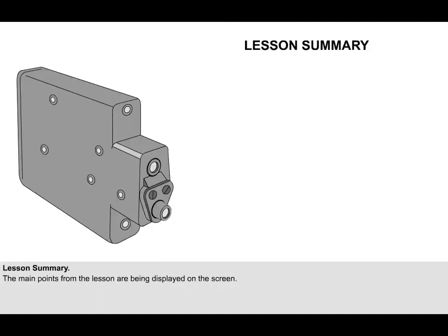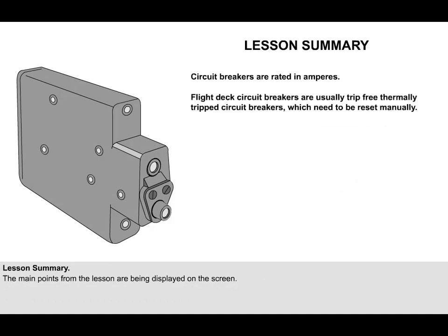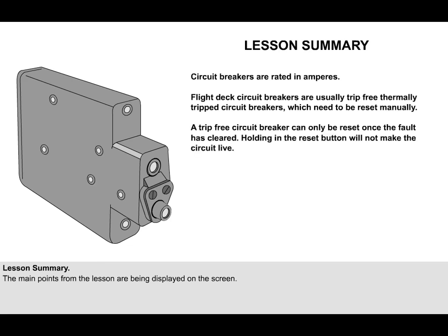That is the end of the lesson. Remember the following key points. Circuit breakers are rated in amperes. Flight deck circuit breakers are usually trip-free thermally tripped circuit breakers, which need to be reset manually. A trip-free circuit breaker can only be reset once the fault has cleared. Holding in the reset button will not allow current to flow in the circuit.